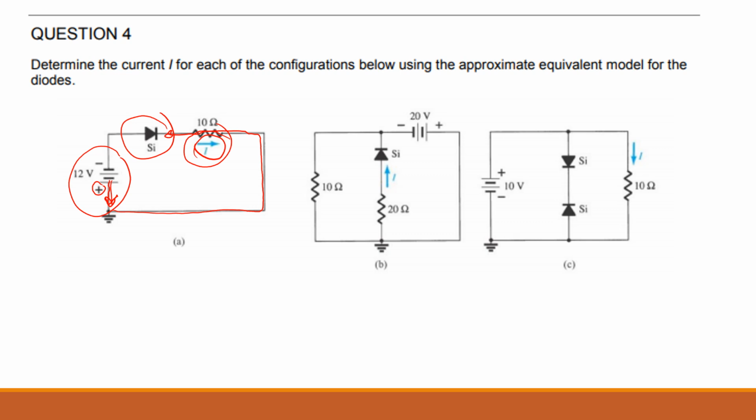That means the current is coming out from the positive side. When you put it on charge, what is happening? It's consuming energy. Then only the current is going into the positive side. So all the other times, any voltage source is supplying energy, so the current is coming out from the positive side. So we're not going to look at the given direction for current.